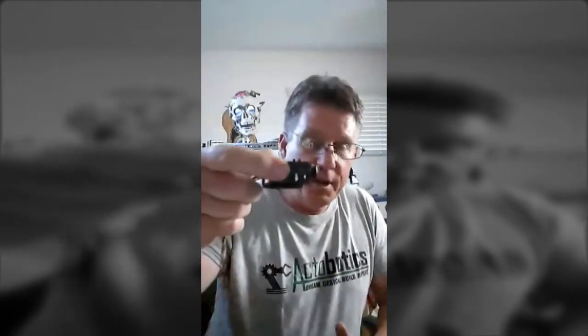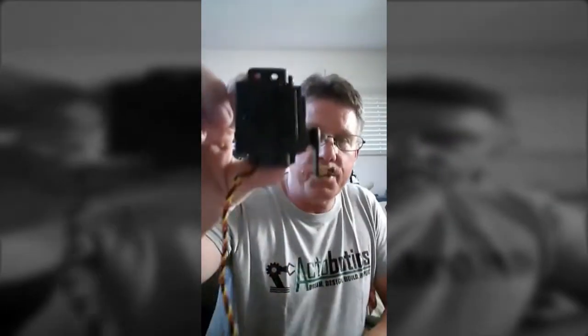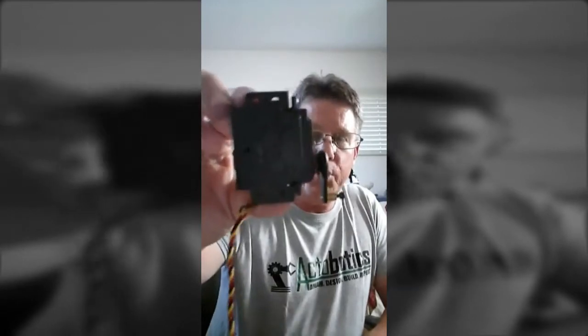If you want to make your servo bracket removable, you can do that as well. You just Vaseline this side of it up really well, set it in there until the platform, the bed, is all nice and solid of the Propoxy. You can take this out, use it for something else if you need it, but you can put it in, then actually drill and tap those holes. So now this bracket is removable.